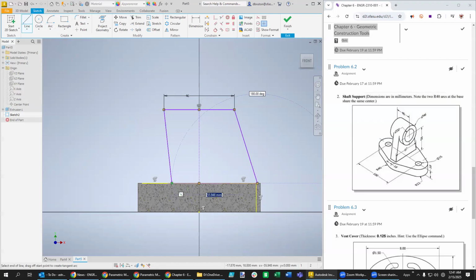It's all about those cases where you accidentally click on something that's a midpoint or the center of the circle. And then let's see if I can move this out just a little bit without causing any problems. Let's make sure we got enough constraints. If we click on this horizontal line, that should be connecting that bottom one. Let's make those two equal right there. See if that helps out a little bit.